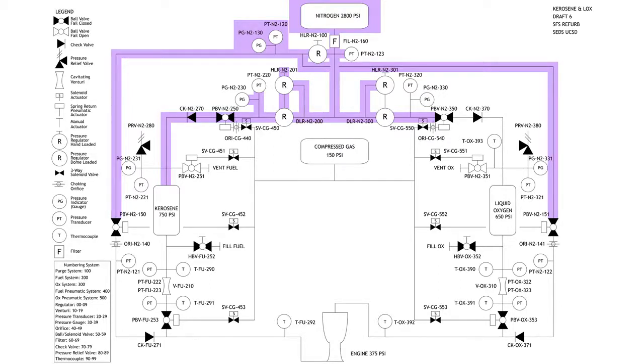Whatever pressure I put into the top of my dome, think of a dome up above, whatever pressure I put into that memory is what it's going to let out through the outlet. That's how these things work. So if I start at 5 psi, it's going to let 5 psi through. If I turn my hand load up here to 10, it's going to have 10 inside this memory, and it's going to let 10 out. Also, the hand load is the set for the dome? Yes, the hand load calibrates my dome, basically.